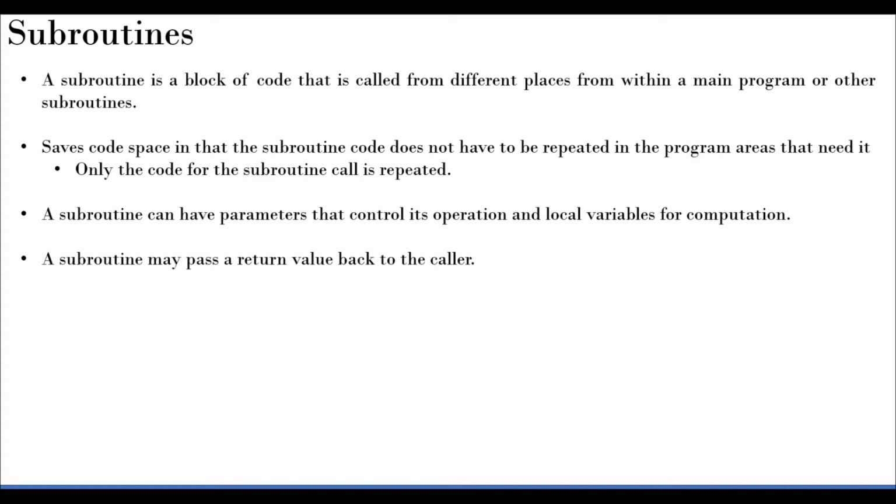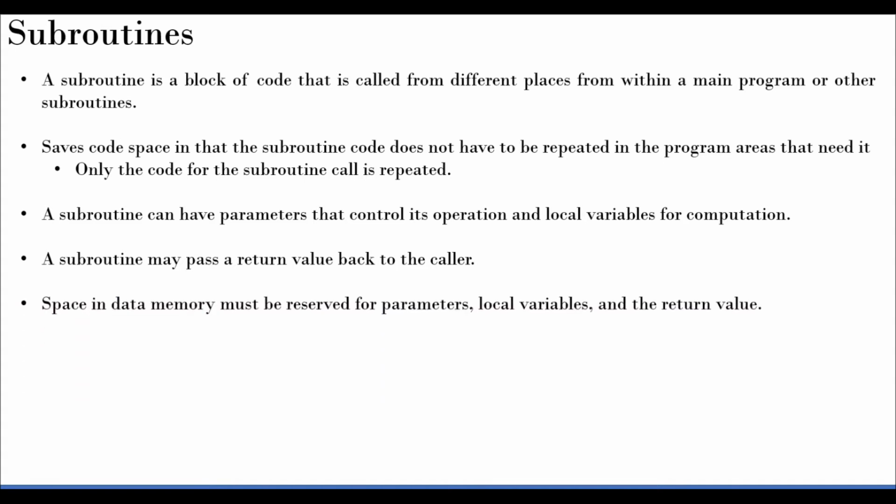So basically, when a subroutine is called, the link register is your friend. The link register will store the current program counter value, and then the program counter will get loaded with the subroutine address, and then you execute everything. The moment the return is reached, the link register content will go back to the program counter, so that you can execute the remaining code in the main function. So play with whatever we are discussing so that you understand it thoroughly. The best way to get used to it is to do some coding and understand it using the Keil software.